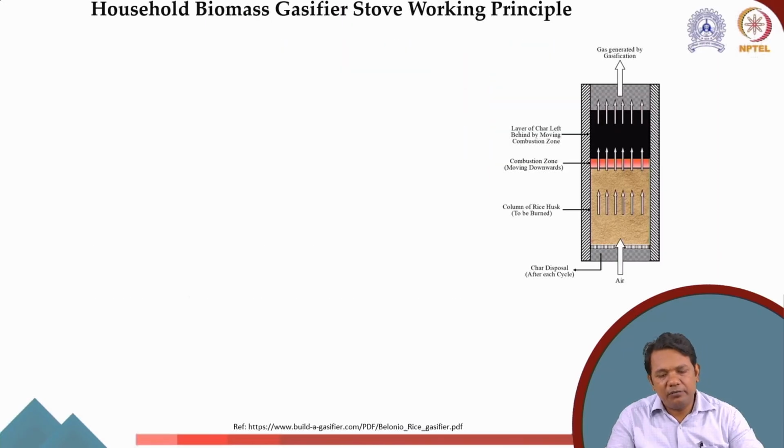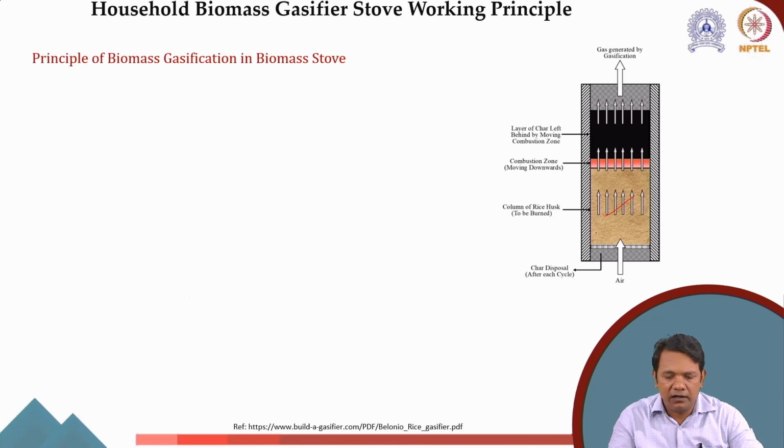Now let's discuss the household biomass gasifier stove and its working principle. The working principle is similar to what we learned for the commercial gasifier. You have the biomass here, and you can see this looks like an IDD design. The air goes in from the bottom, and you have a combustion zone which moves downward, leaving char behind.